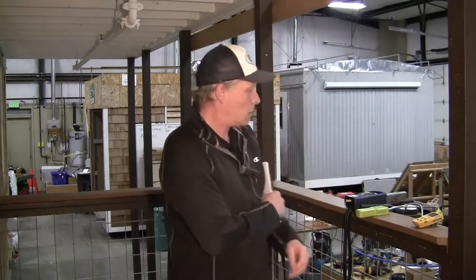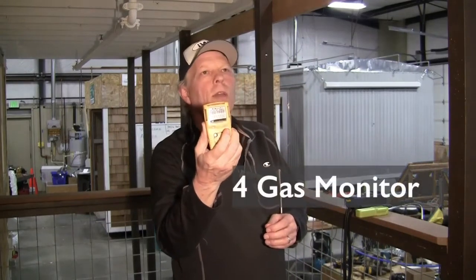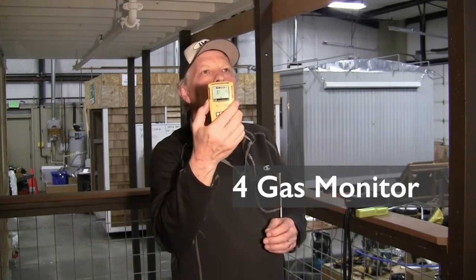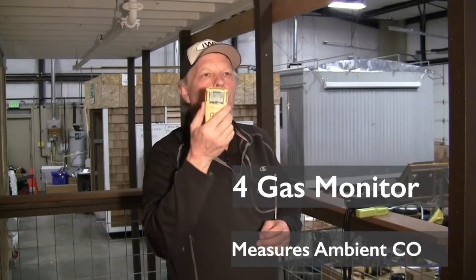So the first one under the exterior section, item number 1, is candidate prepares combustible gas and CO measurement instruments for use. So I'm going to start out here and start my ambient CO meter. It's my 4-gas monitor that monitors for confined space, but it does do ambient CO for me, and I'll have this clipped to my belt for the entire test.